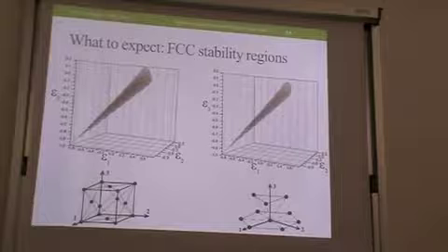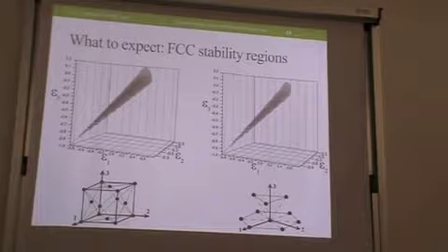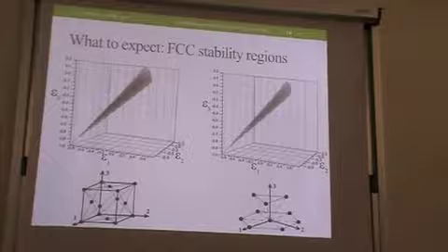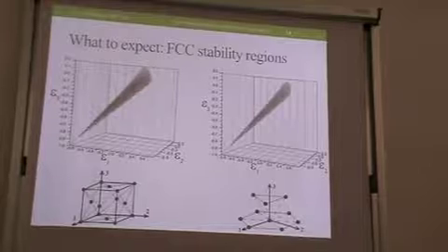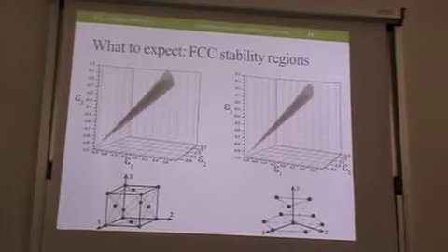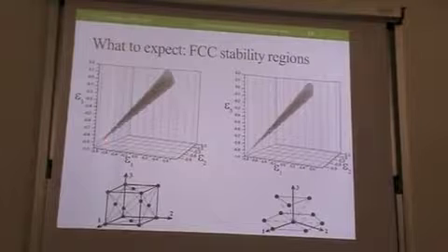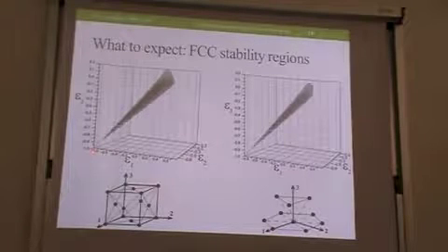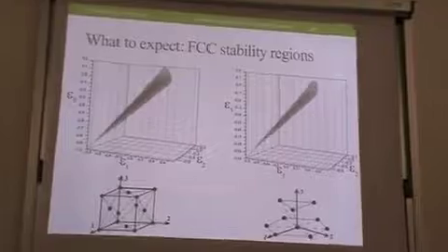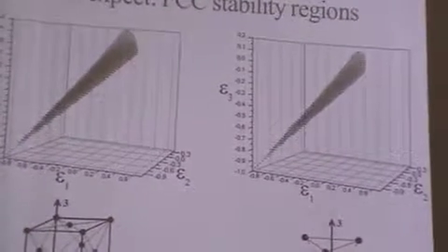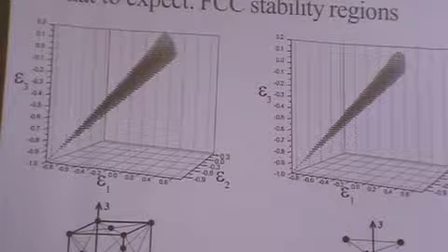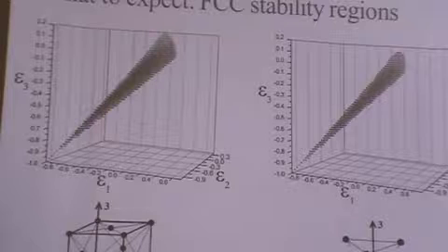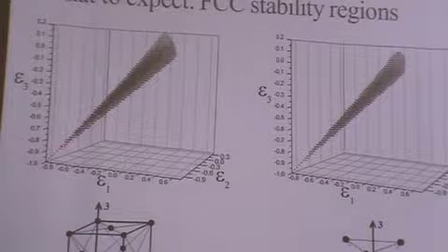So that's the stability region for the FCC in the following strain spaces. Some two cross sections of the full 6-dimensional stability region of the FCC lattice. And you see that there is a tiny tail leading us to the compression of the material into a point, but it doesn't have much physical sense because it actually is a line, and you can't accomplish the compression with such precision. So the real stability region ends somewhere here.